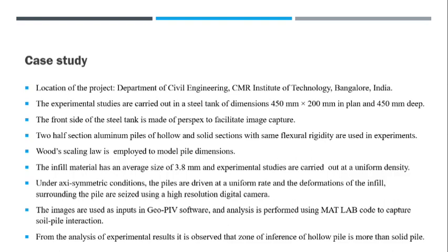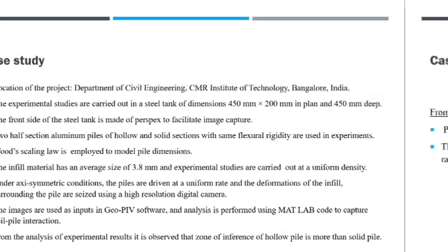The images are used as input in GeoPIV software and analysis is performed using MATLAB code to capture soil-pile interaction. From the analysis of experimental results, it is observed that the zone of interference of the hollow pile is more than the solid pile. Move to next slide.